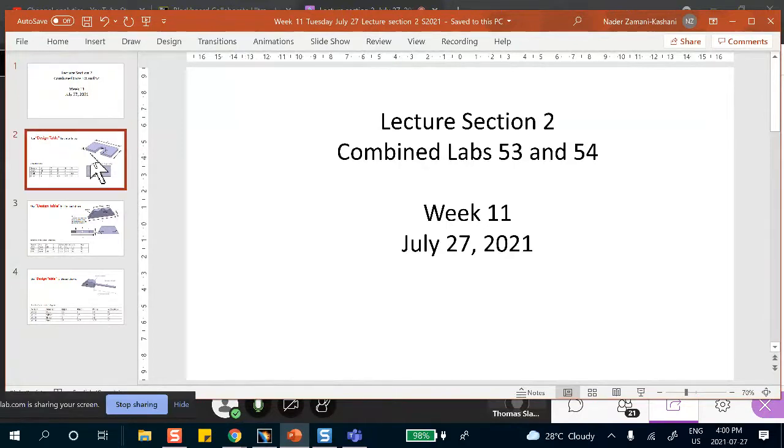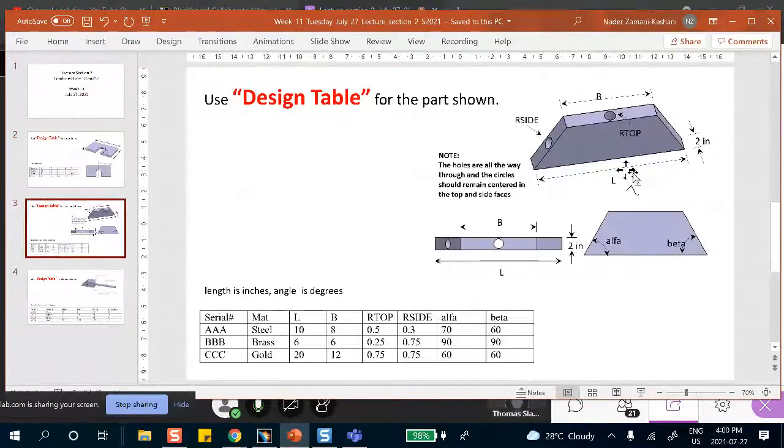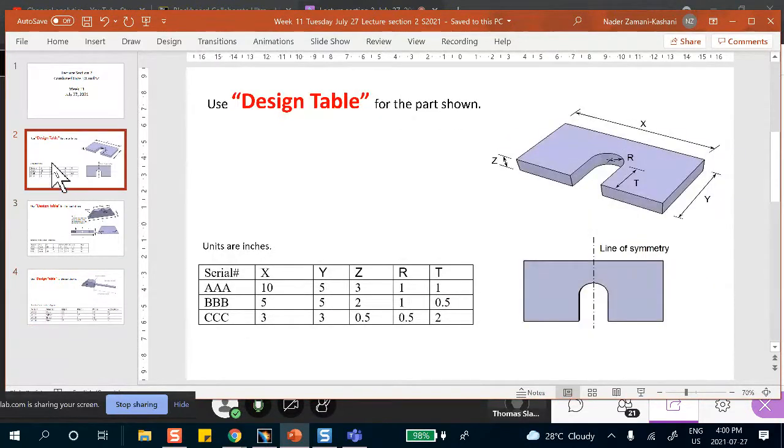Now, in both cases, we went through this geometry and that one and the hammer, and we parameterized this object, this part. And what that meant is that you created some parameters, they appeared in your tree with values, and then you created some equations between the actual dimensions in the database being equal to the value of the parameter.